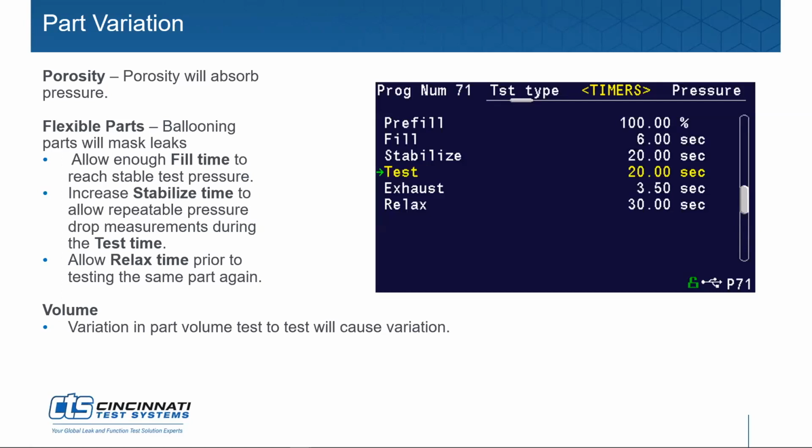A calibration cycle is a two-test calibration where you pressurize a part that is non-leaking, measure pressure loss over time for that known non-leaking part, and convert that to a 0 leak rate. The second test, you pressurize this part, open a leak standard to it, and then measure pressure loss associated with this leak standard in a non-leaking part. So now you're looking at two measurements, a 0 leak rate and a known flow rate for the non-leaking part.